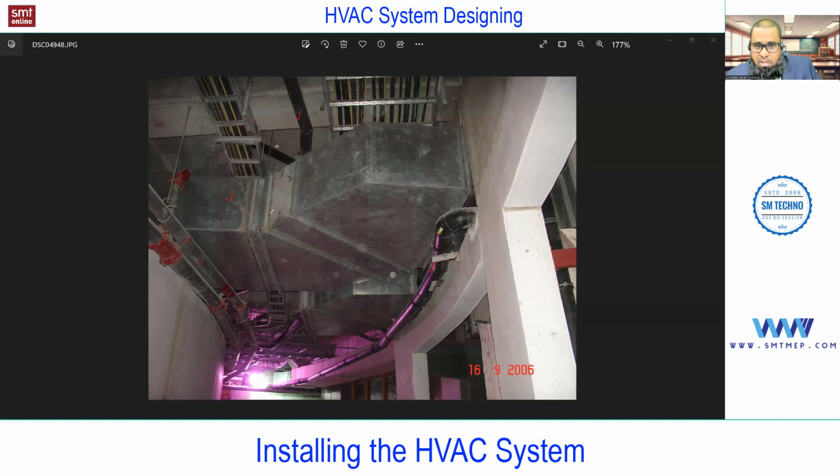Suppose considering all the services, for the height of the duct, if it gets only 6 inch, we cannot design the duct for 6 inch height, except for an exhaust system for a small toilet area. And that is different. But for supply duct for air conditioning, you cannot design 6 inch height, because if you reduce the height, the width will increase, and we have a limitation, the aspect ratio, to maintain. But at this level we will not go into that depth, because the beginners will get confused, or they may panic. Okay, so hope you got the answer to your question.